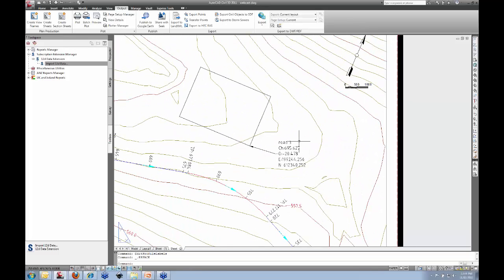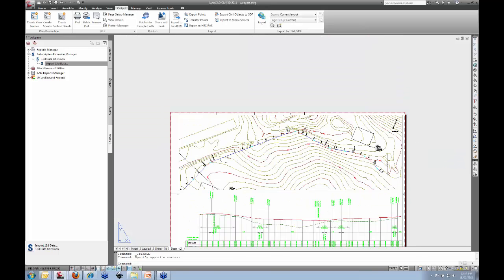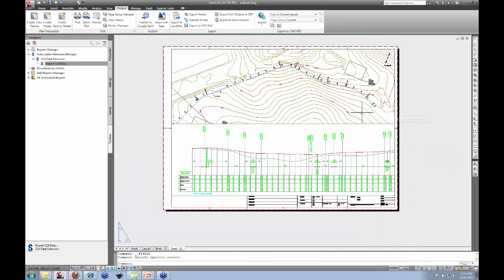This offset label here that I'm holding the mouse over now, that's always pointing up the screen, so the text is always legible. You can do the same thing with the chainage labels if you want, but usually you want those to follow the road direction. But you have this level of control with the software once the templates have been set up correctly, which we've become quite good at because we've done so many of them. So if you want anything else on that, let us know.